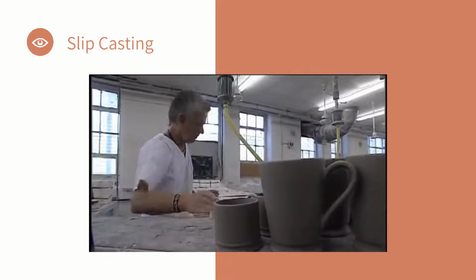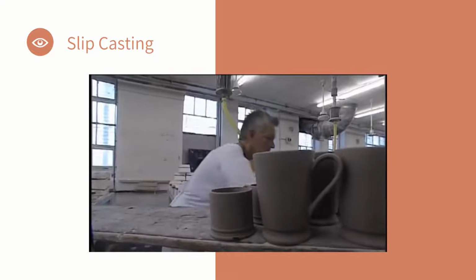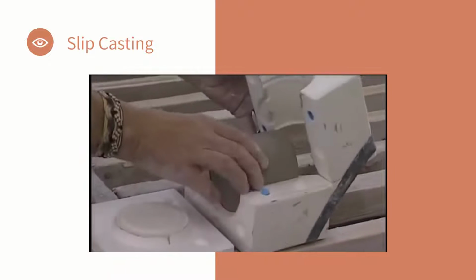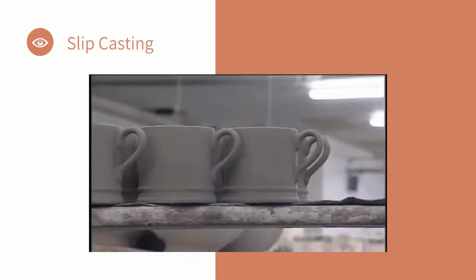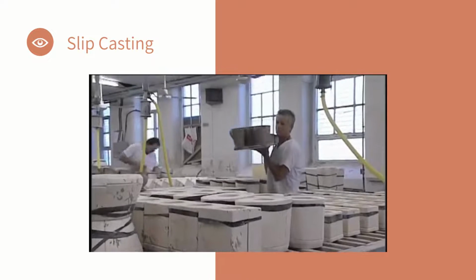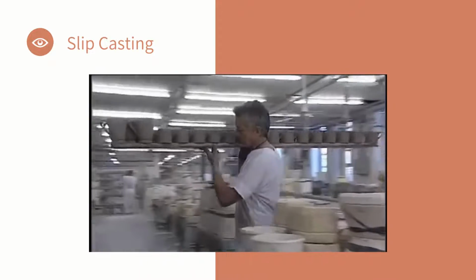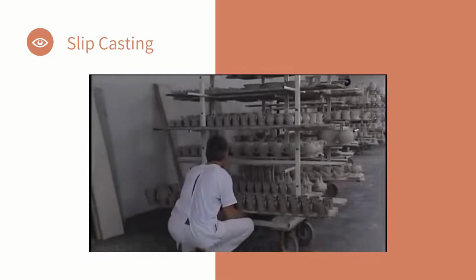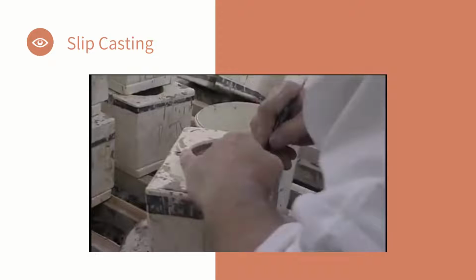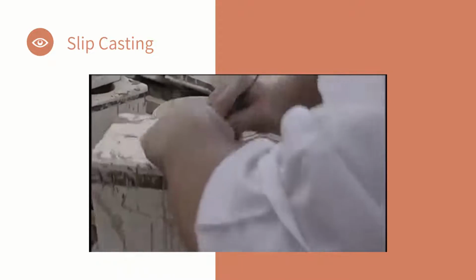This timing is important and precise. Leave a mould too long and you'll end up with a heavier, less elegant mug, which will have to be discarded, the clay reused for another casting. But if the moulds are tipped out too early, the cast will be too thin, so skipping off work early on a Friday afternoon is a bad idea. When the moulds are ready, the wet clay is tipped out, leaving a cast of each shape.